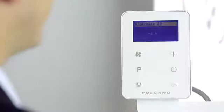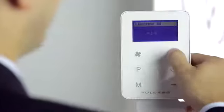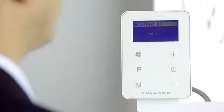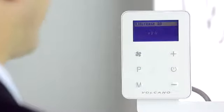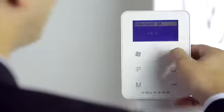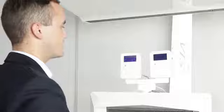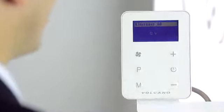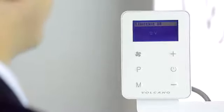We suggest plus 1 volt for objects with a surface area of 150 to 250 square meters, plus 2 for objects with a surface area of 250 to 400 square meters, plus 3 for objects of 400 to 600 square meters, plus 4 volts for objects larger than 600 square meters. 0 volts is the default setting, which does not increase the output signal of our controller.